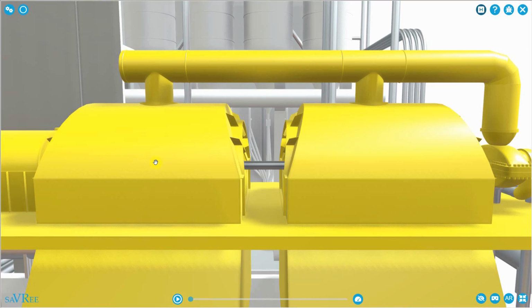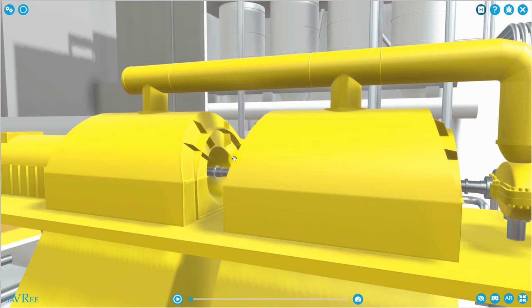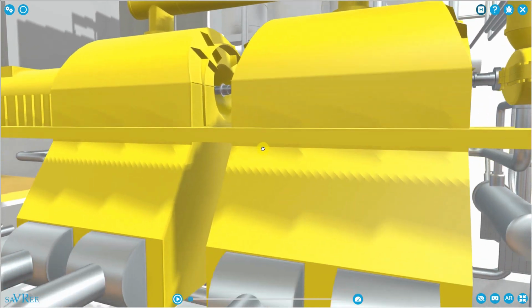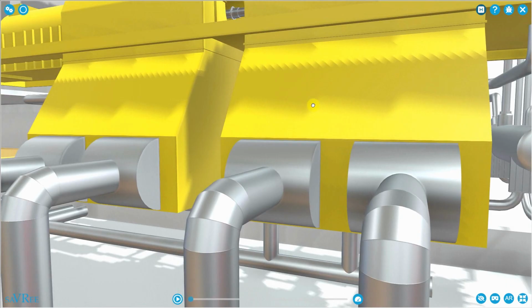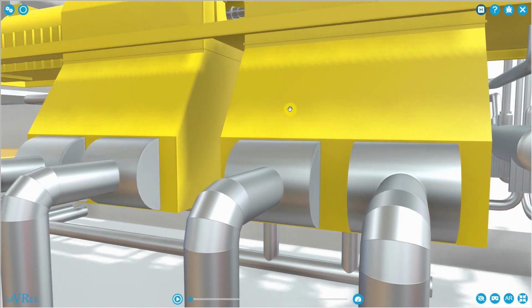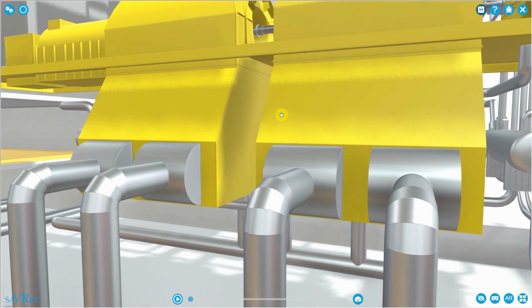But now we've got a bit of a problem. We want to use that water again within our boiler in order that we can turn it to steam and send it back to the high pressure turbine and repeat the entire process again. In order to do that, we need to condense the steam in a condenser, and here we've got two of them. There's one condenser per low pressure steam turbine. And what we're going to do, we're going to cool the exhaust steam from our low pressure steam turbines in order that that steam begins to condense and we get condensate.